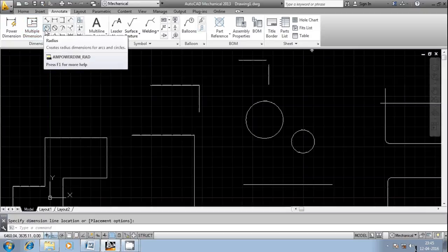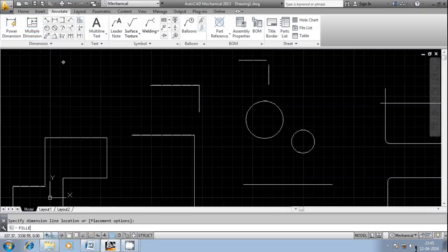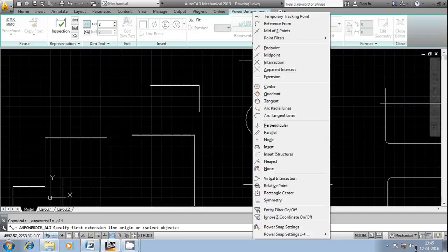Something like fillet. It is asking for the different options. Now select a radius. If you give 100, it may not be possible to get the radius. If you enter it, then select the first radius, select the second radius. You can observe here there is no valid fillet with radius 100. Approximately this distance, the end-to-end distance, must be provided. You can see here this.